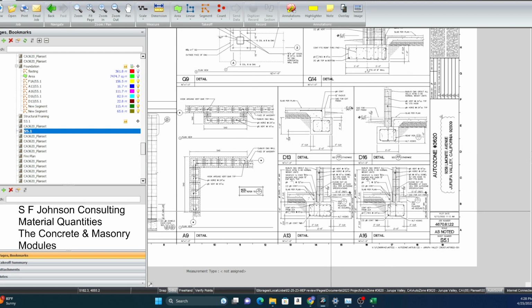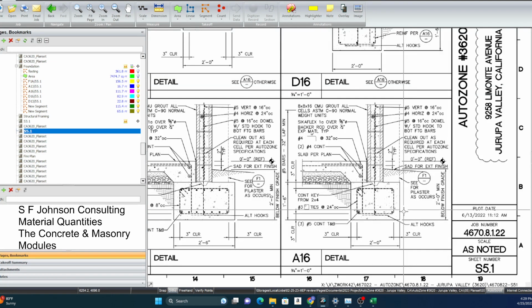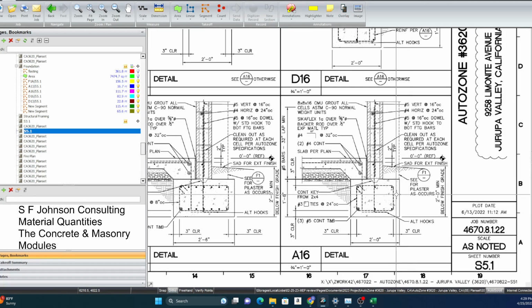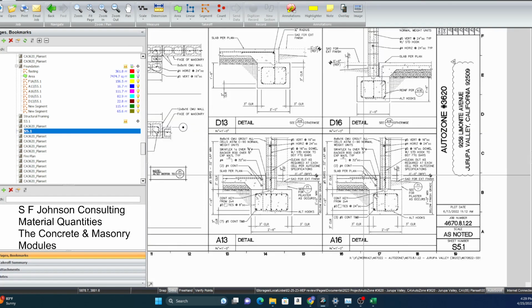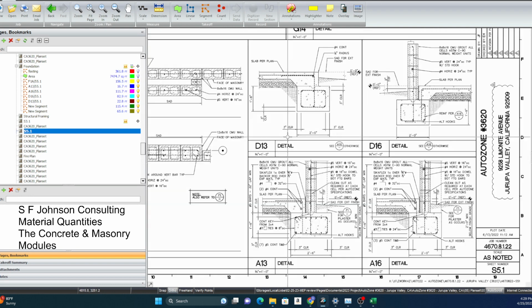If you're forming walls, your plywood has to be the area of the one side of the wall you're forming. If you're forming footings, the width or depth of that wood has to match up, and then we have to have bracing. Blowouts are nice when you don't brace it. Once it's on YouTube, it's nice to watch.